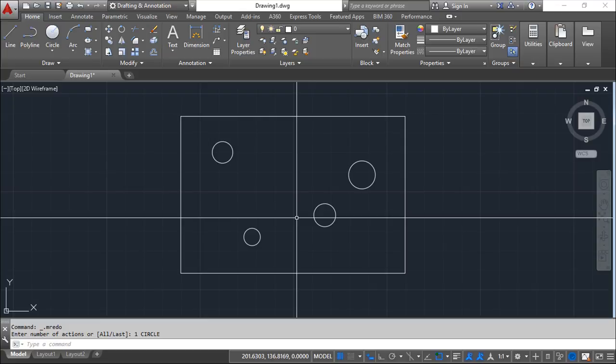Regarding these ordinate dimensions, this is a different type from the other ones we've seen until now. And for your knowledge in mechanical drafting, these ordinate dimensions are used to maintain the accuracy of the machine parts by establishing an origin on the part. This origin is usually an easy way to locate features in the part, such as machine bores or two machine surfaces.